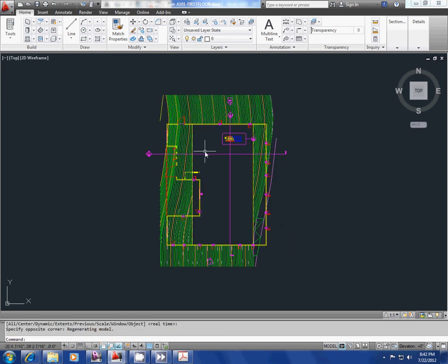So what it's doing, it's giving you that sheet file at full scale, ARCH E1, with all the annotations, 1/8 inch and whatever, and it also gives you a model view of the full scale drawing, 1:1. So it gives you both. If you go to just that view and export just that view, you're just going to get the full scale model file. But that's the benefit of exporting the sheet, is it'll give you the sheet in paper space and the model in model space.